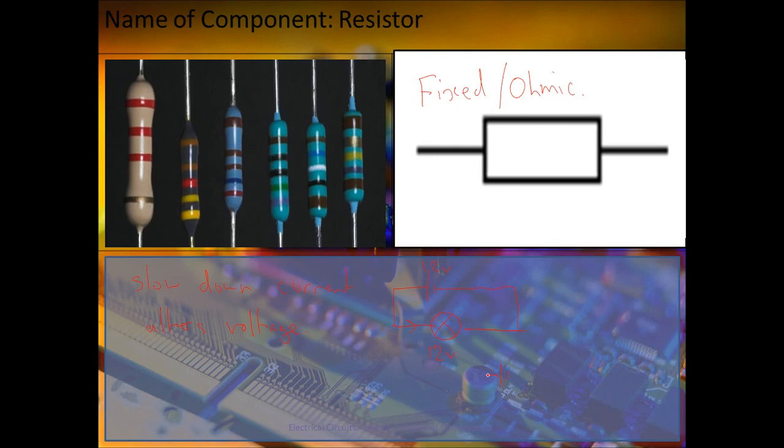However, if we add a resistor in there as well, that resistor would reduce the amount of current flowing in the circuit, but it would also take away some of that potential because the electrons have to push their way through the resistor. So if we had that set up on a 12-volt bulb, depending on the resistor, we might only have 10 volts on the bulb.